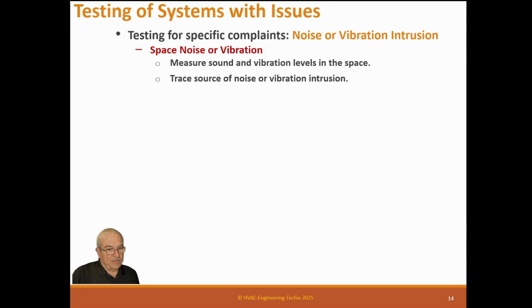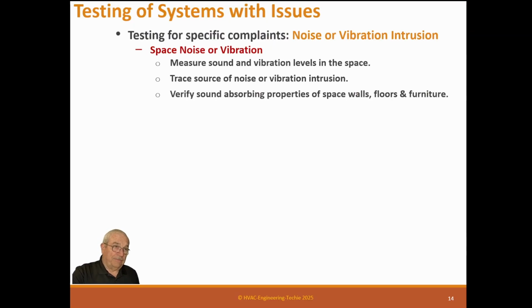I've had systems where we had noise and vibration in a space, and it was actually coming from a pump 3 stories down in a central plant. And it didn't show up anywhere else except this office on the 3rd floor. Go figure, you can't tell how it's moving through a structure. But it turned out the pump had a little problem, it was kind of out of balance. So we balanced it and put it on spring isolation, and the thing went away.